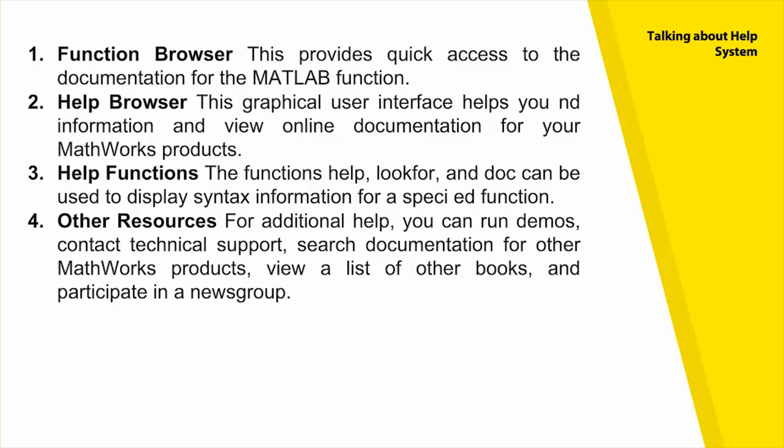Help functions are a set of commands that can be used in the command line to access information about MATLAB functions. These include the help function, followed by the name of the function we want information about. Then we have the lookfor function that allows us to search for a function on the basis of a keyword. Then we have the doc function that displays the documentation for MATLAB functions. Typing doc followed by the toolbox name or function name displays the documentation for the specified toolbox or function.